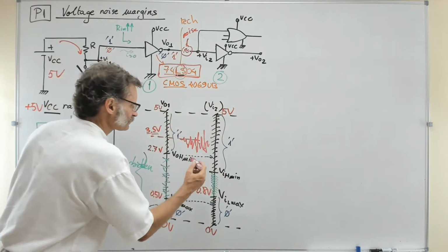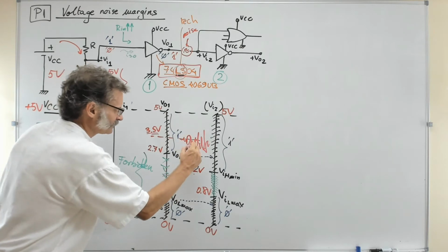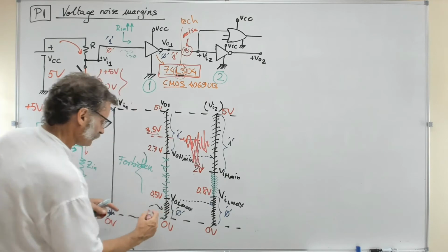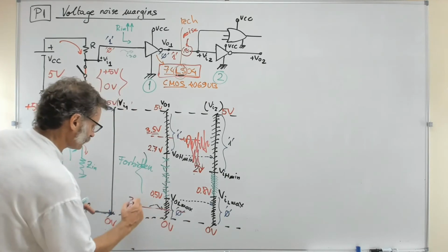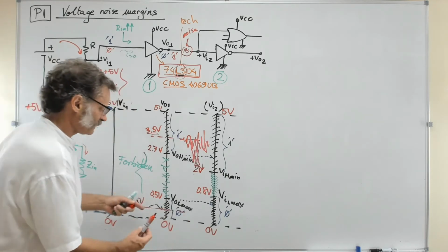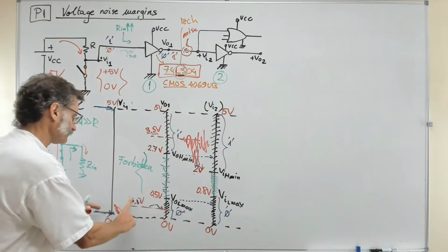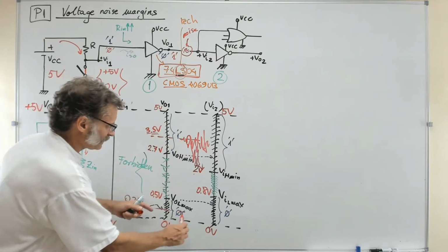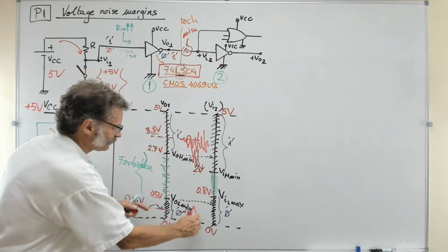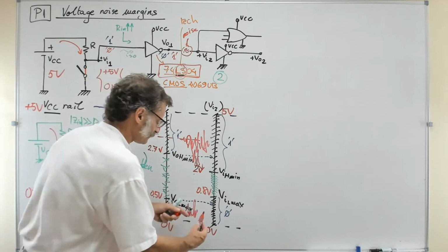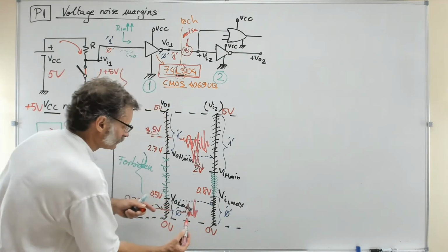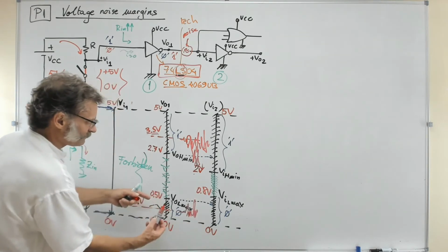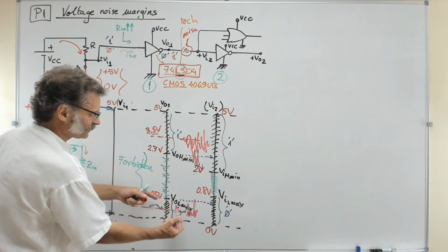The problem is when it goes larger than this and it goes down, or if you are driving, for example, let's imagine the typical value here, 3.5 volts, a typical value of this kind of 3.5, 0.25, for example, and now you have noise picked up from a spark or something. So look at this. If you have a variation here, but this variation does not reach this point, it is okay, it is not detected.